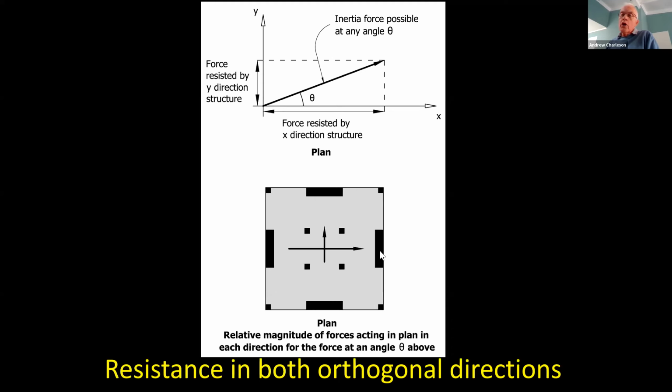These 2 walls are not strong in the x direction, and these columns are quite weak because they're so small and flexible. In the y direction, this wall and this wall will resist the earthquake force. And so with this particular layout, we can make sure that our building is strong in both directions.